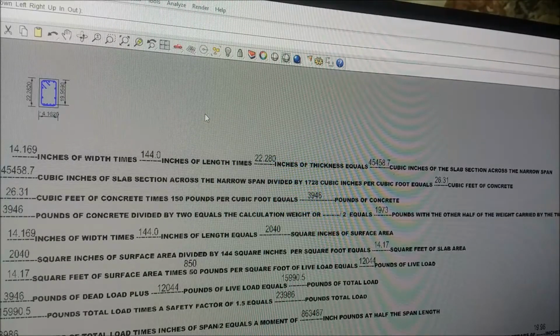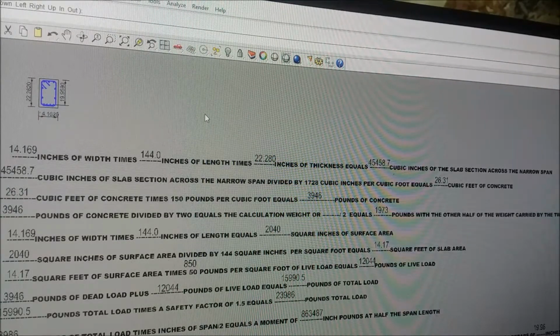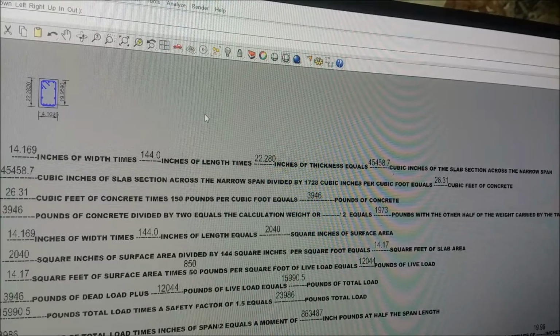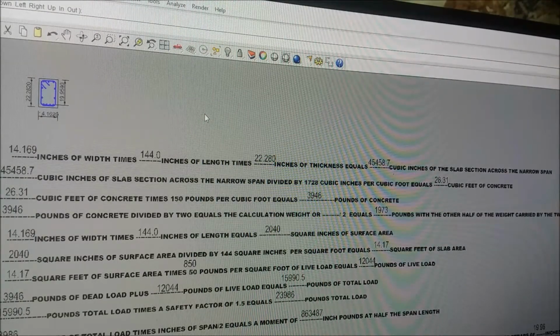And we're going to do 2 calculations with the same load on the beam, though it may not be in reality if you're building something. But the thing is to show the relationship of a tall beam versus a flatter beam of the exact same cross-sectional area and same number of rebars.